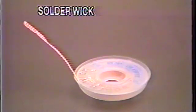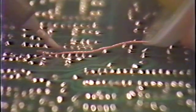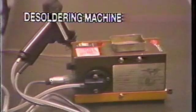Next, we will look at some tools for removing solder. This is solder wick, which uses capillary action to remove molten solder. Here is a desoldering machine which uses a vacuum pump to remove the solder.